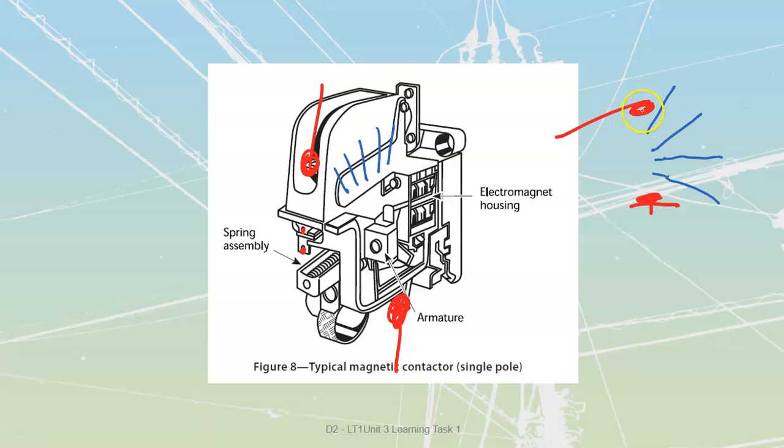That movable contact, when it goes down, is going to go tick, tick, tick, tick, tick. It's going to make contact. It's actually going to brush by each of these. Not a lot of contact, but they're going to be insulated individual ones inside of that contact over there. But they're going to be making contact as this thing closes in. They don't do much when I'm closing in. It's later on when I am pulling this out that they're going to go and do stuff. They're going to go and take that arc.